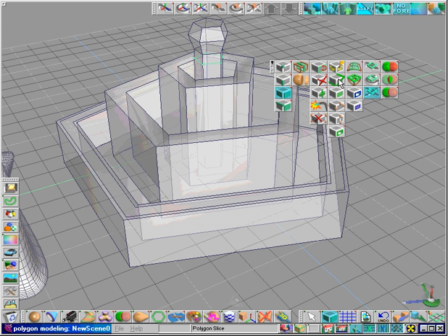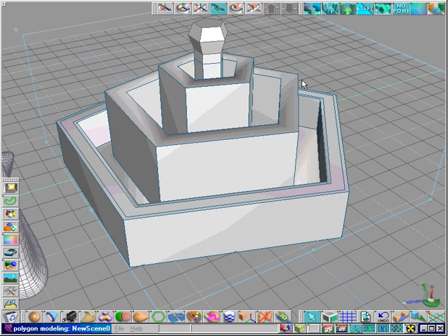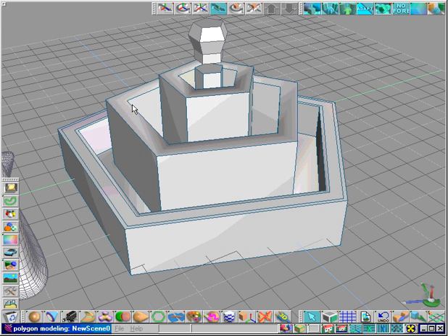With the edges still highlighted, we click on the Polygon Slice tool and select a point above the highlighted edges. All the faces on that side of them are selected. We can now use the Separate tool to cut that part off. The previous non-selected part becomes highlighted. We now have two separate objects.